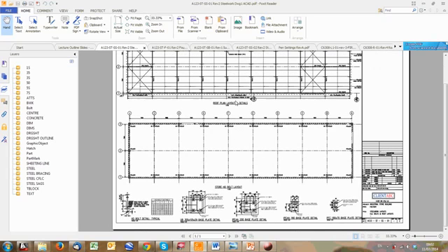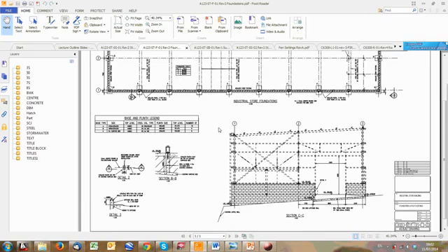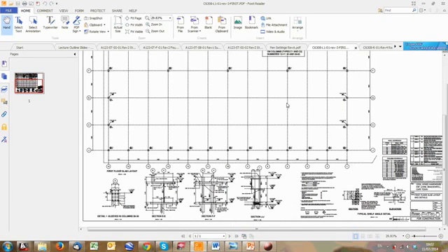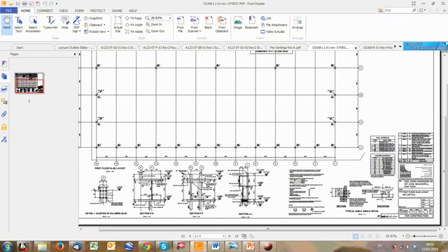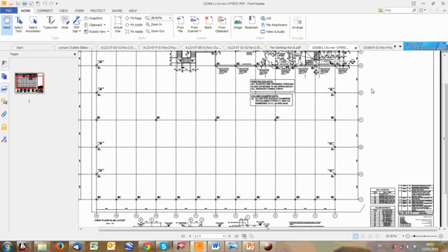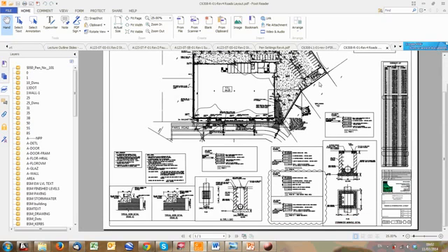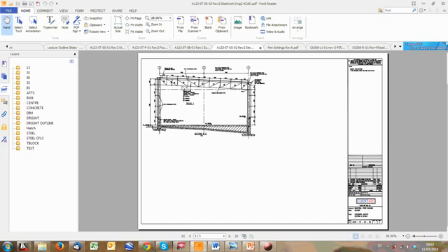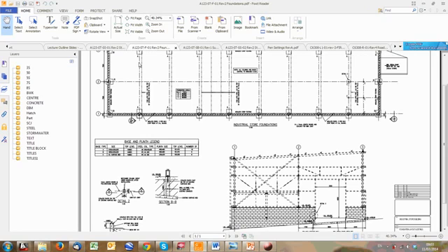So it is layouts, details, sections, specifications, schedules, any detail he requires to produce the structure safely. This is a roads drawing, so we'll have layerworks information, stormwater details, steel details, etc. You need to think about what information do I need to put on this drawing such that if I was the contractor, I could build it.